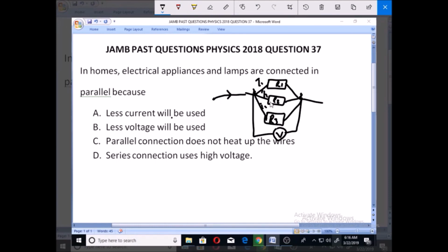So that is what we have in a parallel connection. And in a parallel connection, voltage remains the same and the current divides for each. That is one property of a parallel connection, so that 220 volts is there for all of them, providing the current required to take these loads.